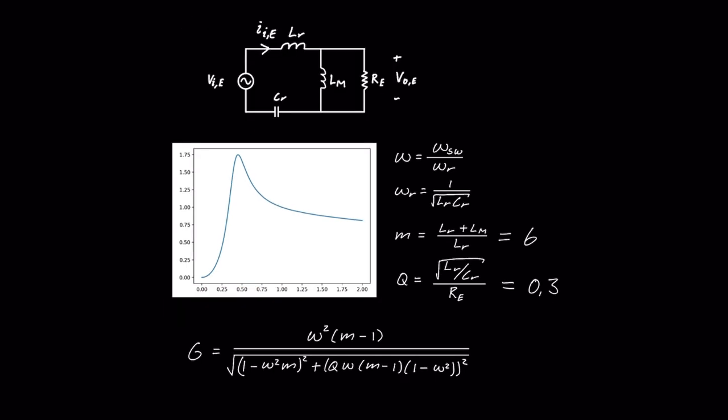By doing a first harmonic approximation, we get this circuit here for the resonance tank. And then we can derive that this is the voltage gain, which is shown in another video that I made. So M is constant and Q is varying with R_e. So this voltage gain curve is dependent on Q, which is not constant. It depends on the output resistance.